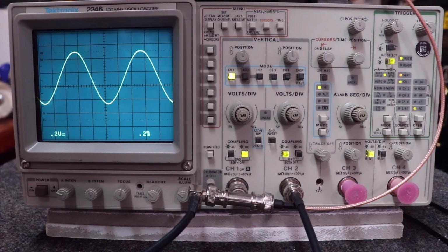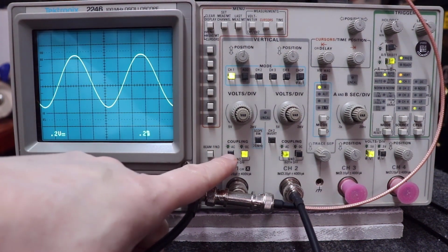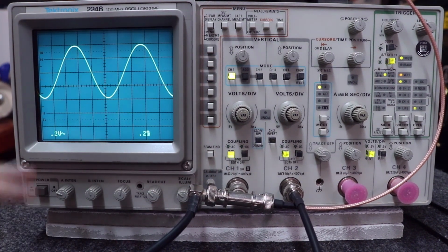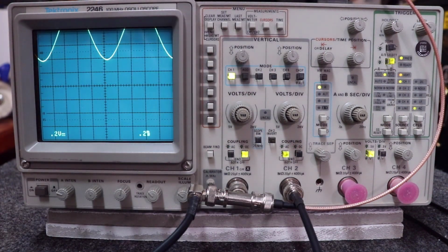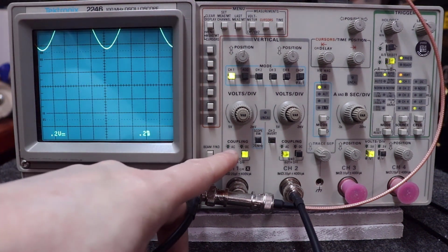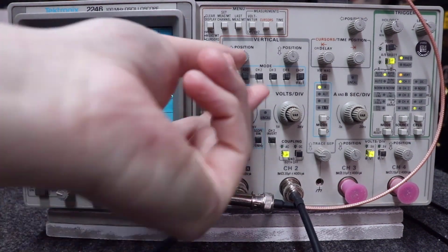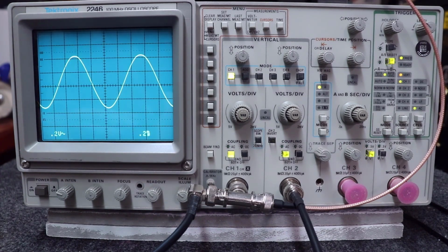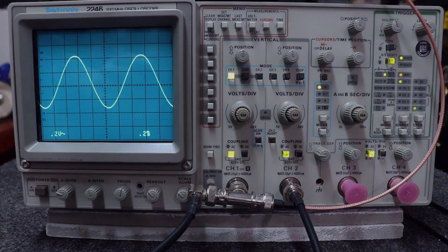So you can switch this unit over to what's called AC coupling, and all it does is put a coupling capacitor in line with this signal, and it removes the DC component. Watch this. Let me put it back on this. Watch, I'm going to move it up here, okay? So it's starting to go offline because I've got this DC component added to my AC signal. Watch what happens when I AC couple it. Brings it right back down, and then I can use the position if I want to hover it around the 0 mark there, okay? You're just removing the DC component of the signal feeding into this oscilloscope.